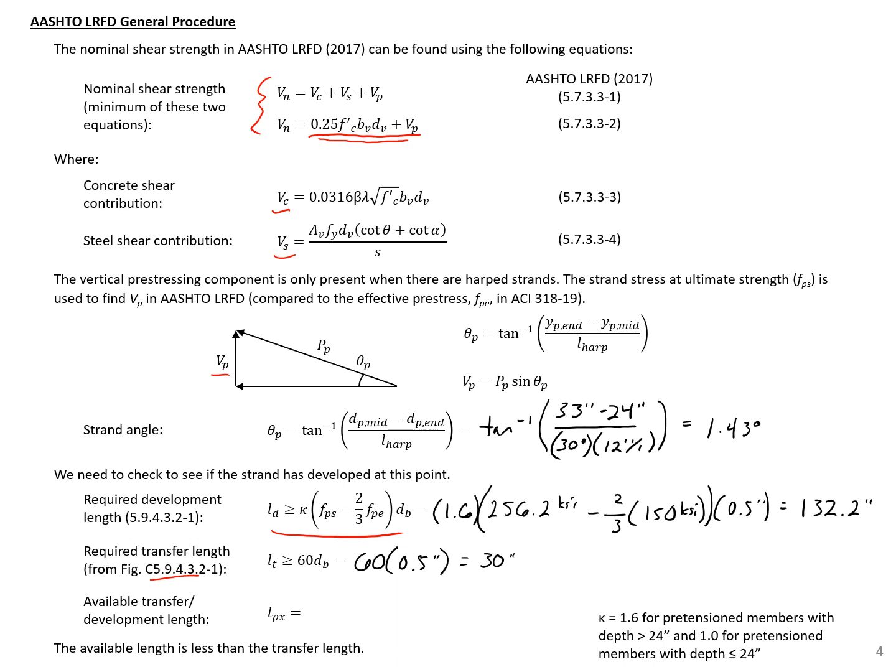Our available transfer length is our 24 inches, the distance from the center of our bearing to the point of interest for us, plus half of the bearing because our beam goes to the end of the bearing. So we have an 8-inch bearing, so we're dividing that by 2, and this will give us a value of 28 inches of available development length.